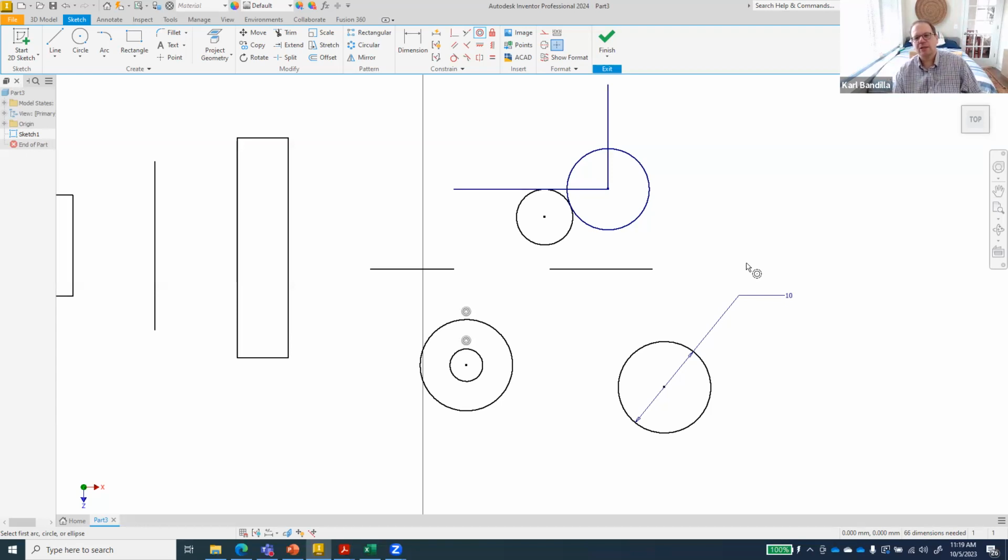You may have run into this issue when you were doing your sketch and you changed one of the dimensions, and everything else shifted in a weird way. That's the same problem. However, always remember that you have that little lock constraint. So if there's something where you say, okay, I know this is where it is, it's supposed to be there, then just use that and you're in good shape.